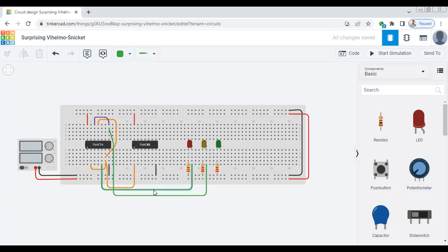So now the next thing is what? Now we connect the 9th number pin. So here this one is our 9th number pin, 7, 8, 9. We connect the 9th number pin to the input of our AND gate. So we take that wire and connect that wire to the input of our AND gate, and we give the color orange to the wire for the input,